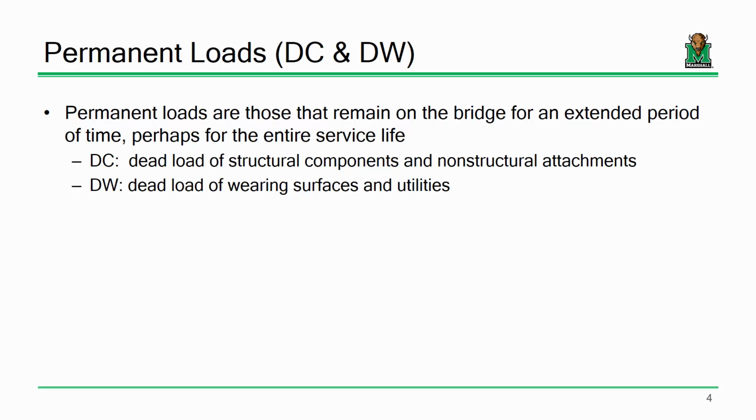So let's start off with the easy part. Let's start off with the permanent loads, the loads that always sit still. In other words, the dead loads, okay? Now, we really have two dead load force effects that we need to consider for highway bridges, specifically the components that we're dealing with, and those are DC loads and DW loads. If we were looking at substructures, we might have earth horizontal pressures and things like that. But for what we're doing, DC and DW.